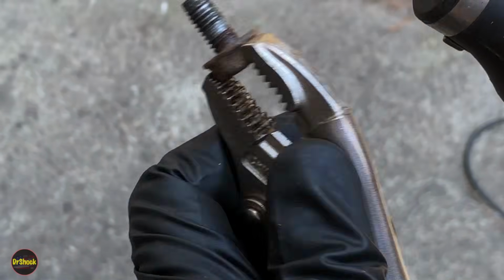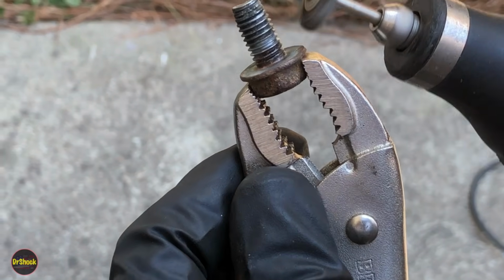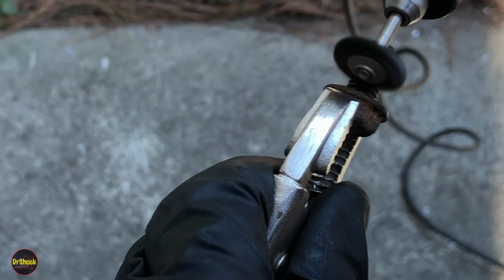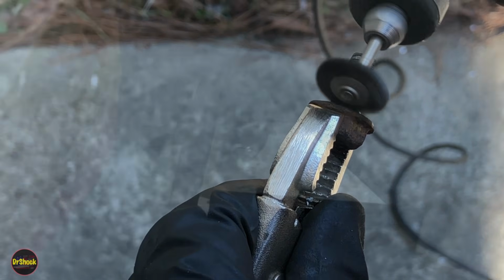We're just going to keep going like this until we can clean this up as best we can and reassemble it, and we'll see if it has any bearing on it. Otherwise, we'll continue with the last step in the service manual. All right, guys, after you brush everything off, the last thing is to brush inside. We're going to use this little brass pipe cleaner just to make sure that where the threads bite, we don't have any oil or corrosion in there as well.